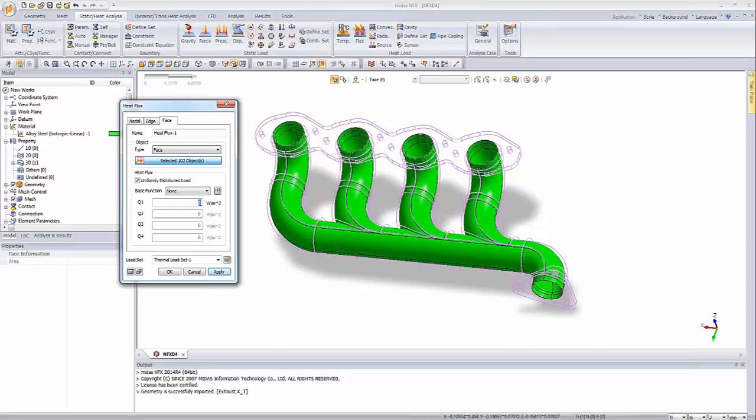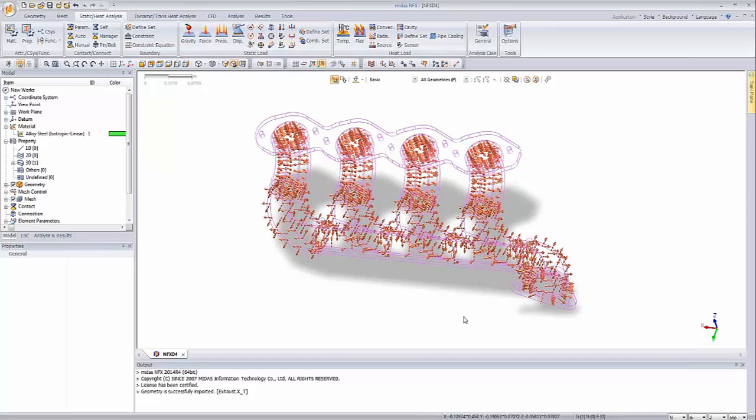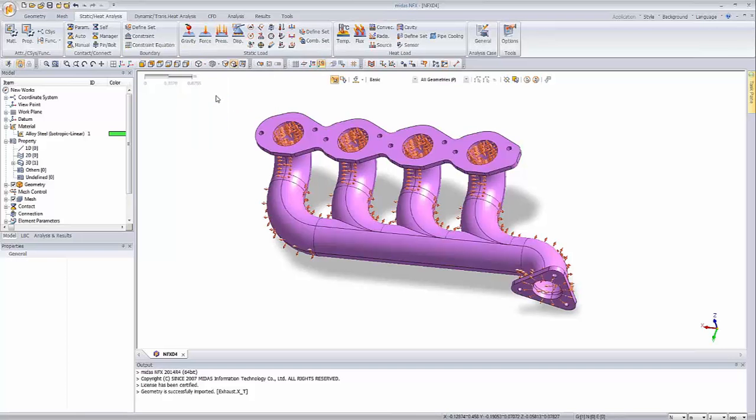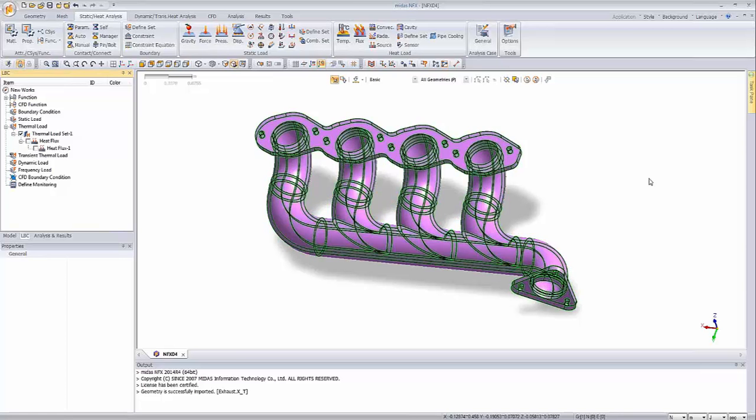Now you know. Okay, so let's apply the value for heat flux. It will be 40,000. And let's click on OK. So as you see, the whole job has been done. So we are saving a lot of time. Let's change the display back to the previous state, and let's click on shading and line. And now I'm going to the slot and boundary condition, and I will hide the display of the heat flux because I want to work in a lighter view.